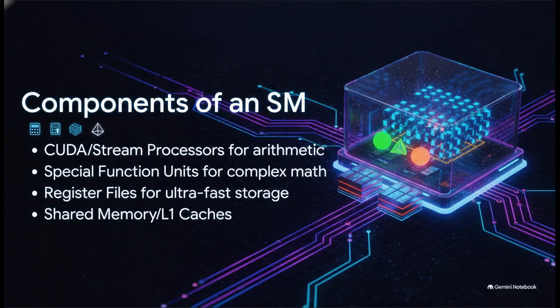If we look even closer at the components of an SM, we see they're packed with highly specialized tools. They contain CUDA cores, which act as the arithmetic logic units for basic math. They feature special function units for really complex calculations, like trigonometry. But crucially, they feature massive register files and shared memory. Because GPUs rely heavily on hardware multithreading, they can hold hundreds of execution contexts active at once. If one thread stalls out while waiting for data to load, the SM instantly switches to another thread, completely hiding the latency. Basically, no core is ever left sitting idle.